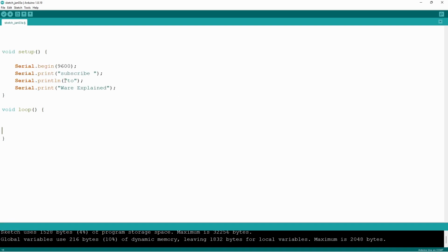This is a good example of what I mean. Obviously, I started off with the Serial.begin. You have to start off with this command in order to activate the serial monitor. However, I do utilize the concept of ln pretty well here. The first print command does not contain the ln. Therefore, whatever is printed after it will also be in the same line. You have to take into consideration spaces. You do have to manually place them. I could have removed the space here and added it before the T. It doesn't make a difference. However, it just has to be there. Otherwise, it will be joined together. However, I do make use of the ln onto the new line, just so that everything is not congested onto one line on the script.